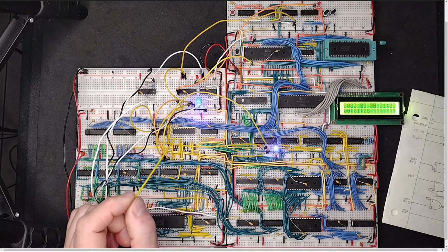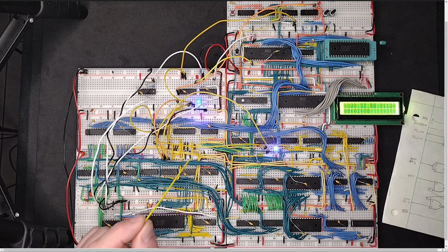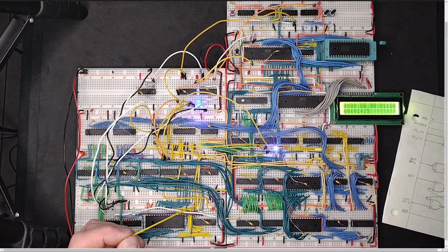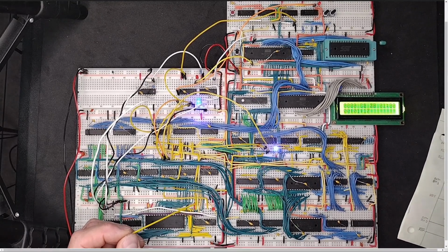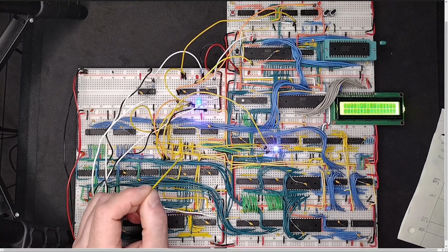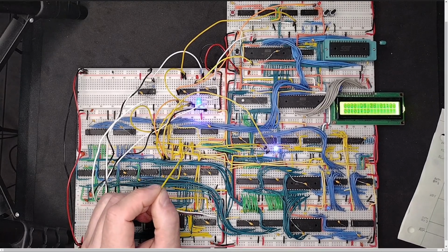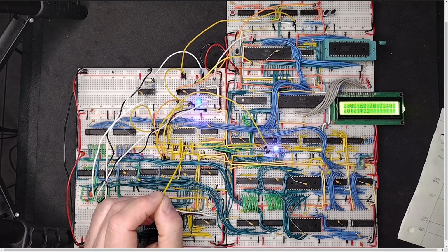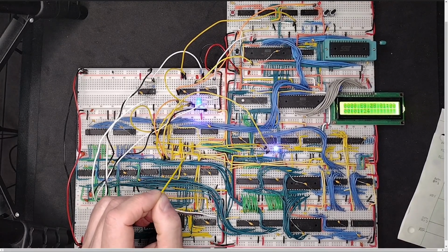In the meantime, I am using the video interrupt, the video blank start interrupt, a vertical blank start interrupt. I already explained how that's latching there. Then I have this bit here, which, if you recall, is the VGA signal. In other words, this just tells whether we're in the vertical blank interval or not. That is running up to bit 7 in this latch, so I can use that bit to determine if I'm in the vertical blank interval or not.